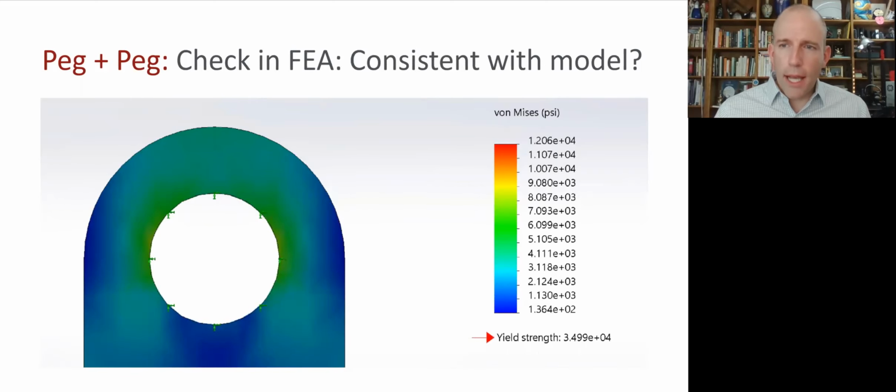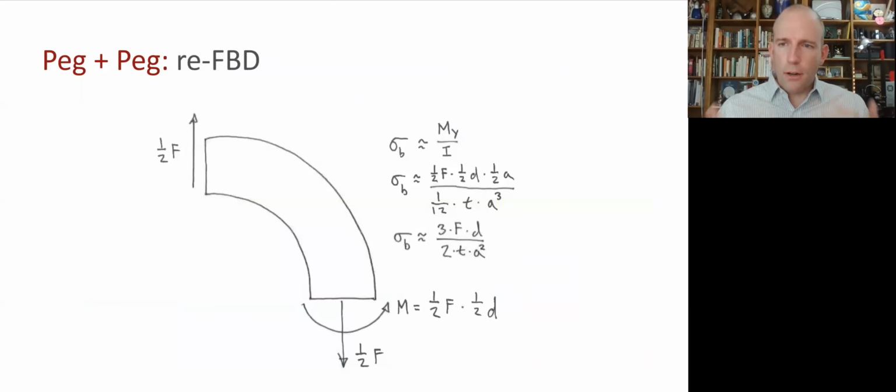And you can see right away that, yes, our guess is a little bit on the optimistic side. The pattern of stress across this section is not even. It's pretty low on the outside, and it's pretty high on that inside edge. So we are getting some bending, and that's having a significant effect on the stress. So we could try to capture that in a slightly better mathematical model, which might inform our intuition and result in better design. So if we return to our model,